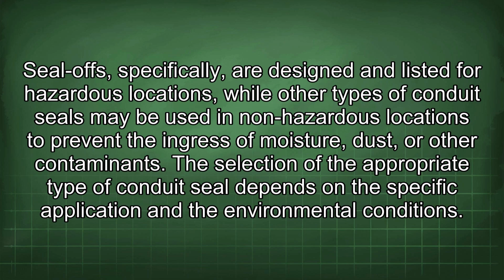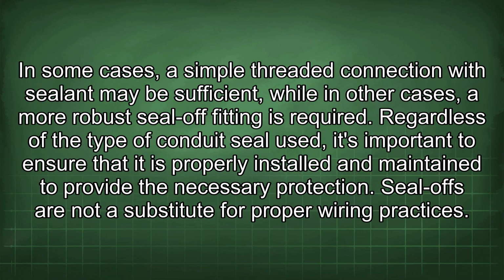The selection of the appropriate type of conduit seal depends on the specific application and the environmental conditions. In some cases, a simple threaded connection with sealant may be sufficient, while in other cases, a more robust seal-off fitting is required. Regardless of the type of conduit seal used, it's important to ensure that it is properly installed and maintained to provide the necessary protection.